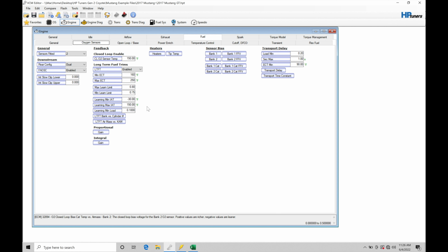This is the target air fuel we want to run at when we're in those conditions. This gives a balance of emissions and power output from the engine, and also fuel economy is another aspect to this, but that's what OEMs always shoot for at idle and part throttle conditions, stoichiometric. That's 1.0 lambda, or again, 14.7. We're talking about the gasoline petrol air fuel scale.